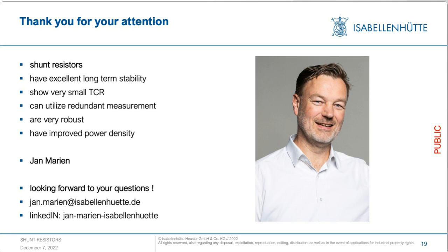So if you're using this shunt and putting it into an application, you can read out these values during manufacturing of the device and use this in the calculation of, for example, the battery management system or the motor controller or wherever you're using the shunt to compensate very precisely for all temperature and also for all initial errors without the need to calibrate in system.